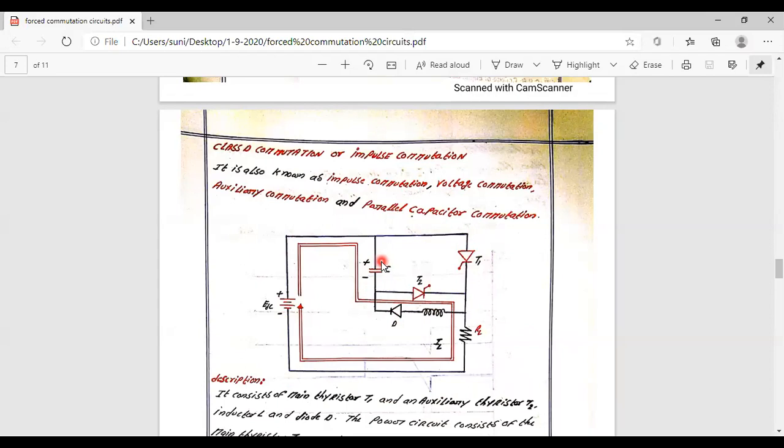That conduction path is going to be from positive to this T1 to this inductor to this diode to this negative plate. Whenever it is completely discharging, the polarities are going to be reversed. You are going to have a positive plate in the lower and negative plate in the upper. Okay, so this is going to be happened.